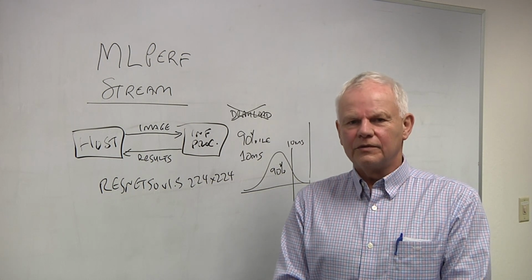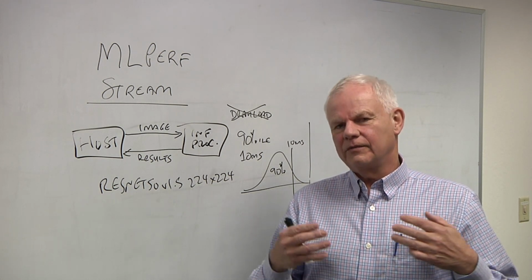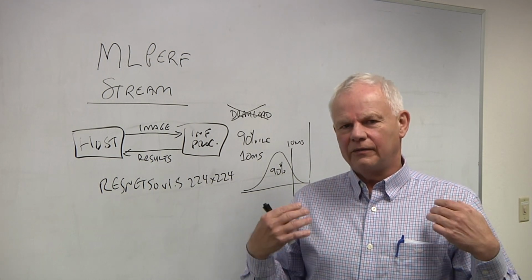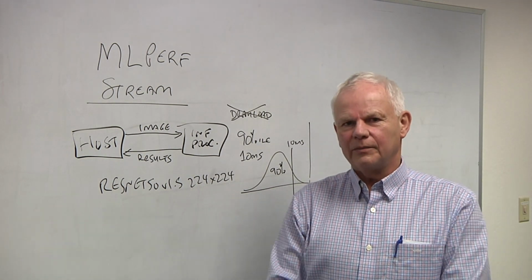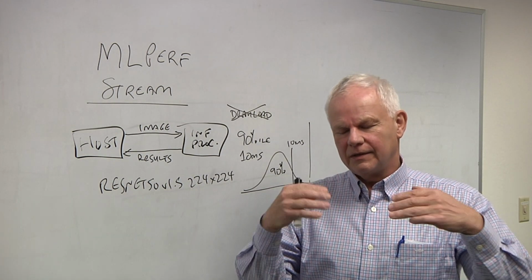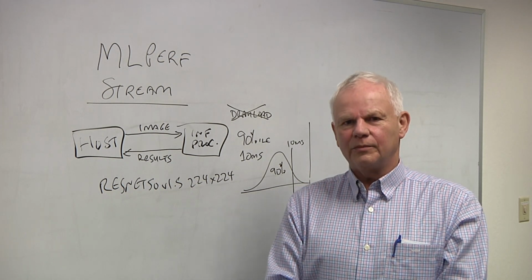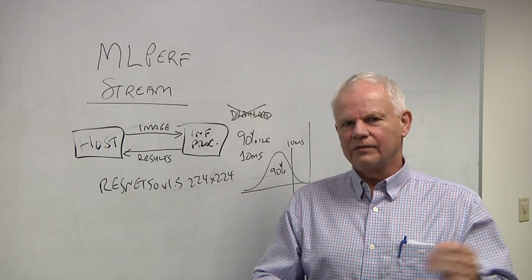So people know what they're designing for, and the more that you're designing for longevity, the more you're going to back off on frequency, you're going to reduce operating temperature, because all of the fundamentals of what can go wrong in a chip get worse as you have higher temperatures and higher frequencies.